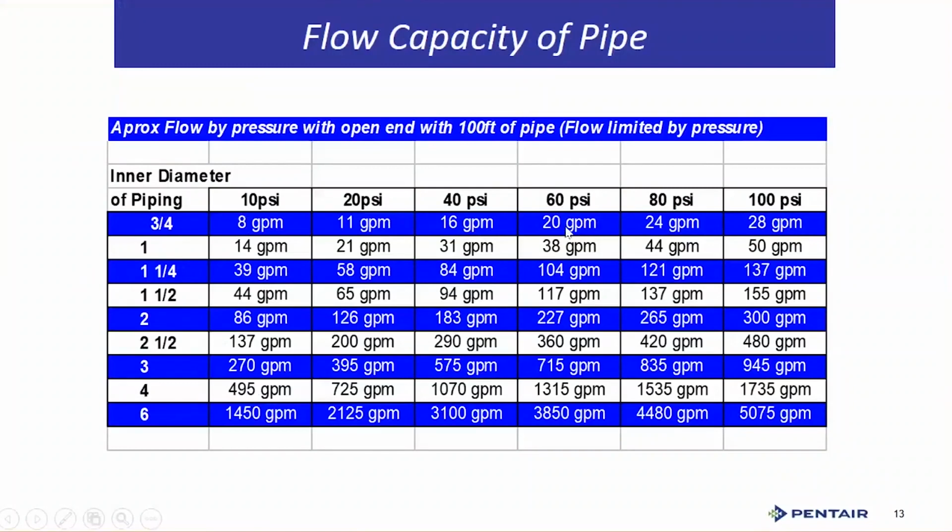Well, 20 GPM times 15 is 400. Oh wait, I'm sorry, I can't do math this morning. 300 gallons per minute. Well, he's got a valve on that system that can only do 60, pushing way too much water through that resin. He's wondering why he was getting pressure drop. The system couldn't handle peak flow of all the hoses hooked up to the system.